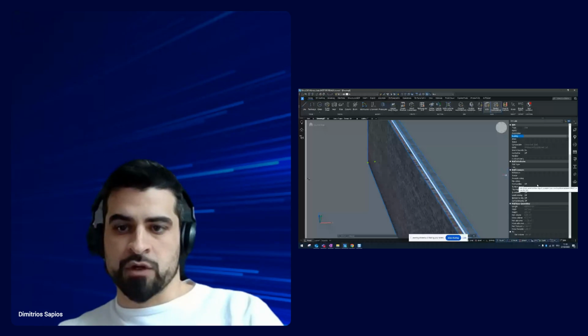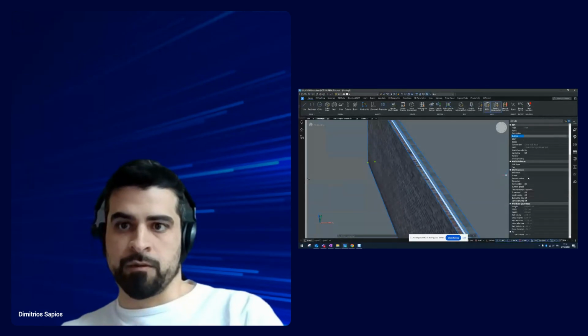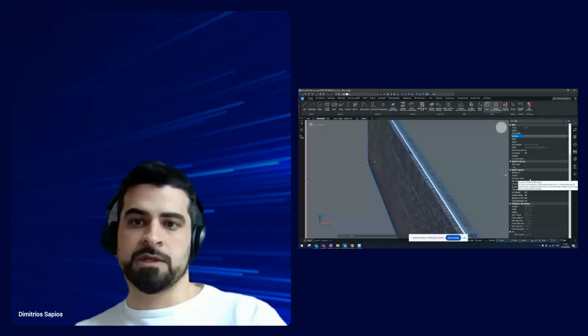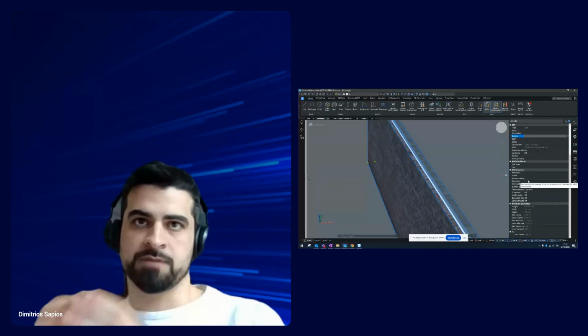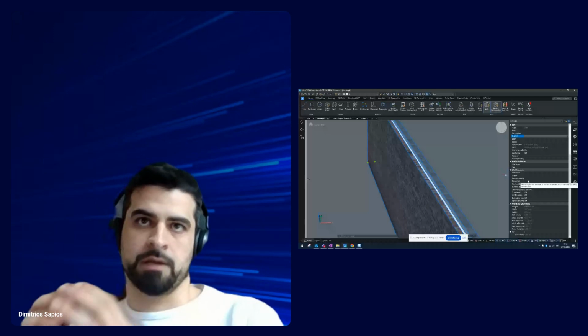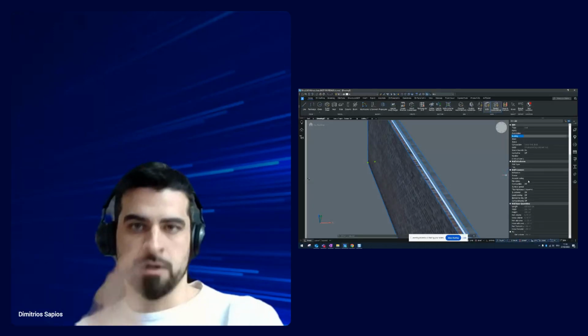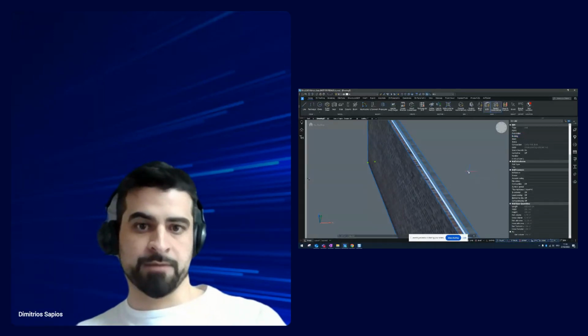Of course, during the creation of a project, not all of that information is relevant, and here comes the importance of the IDS file. We can isolate and create a really specific list of those features, which can then later be filled in and exported.